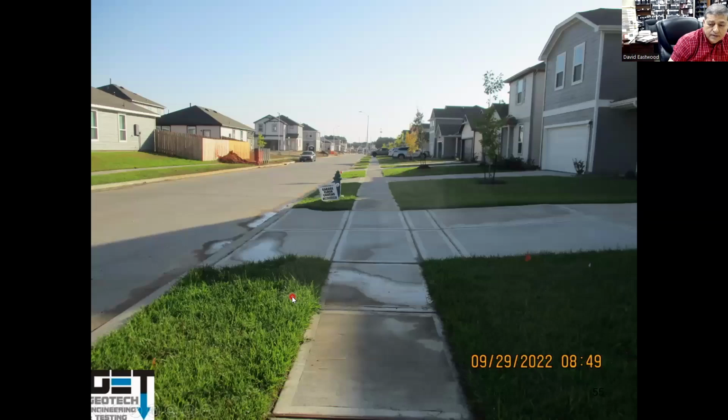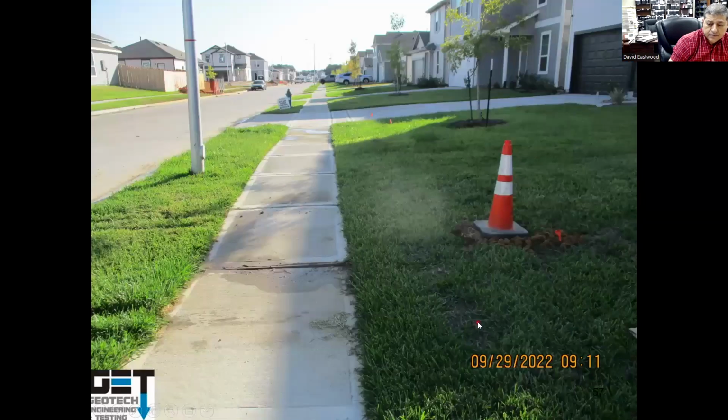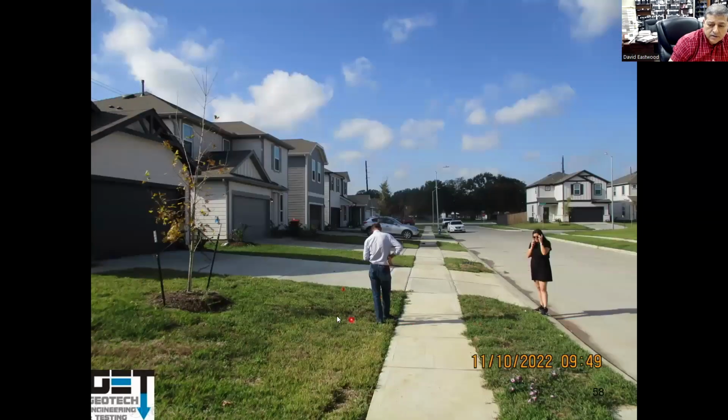Subdivision. Some of these subdivisions, they go in there and turn on the sprinkler system. Soils are sandy. When they get saturated, they start settling. So the sidewalks start settling. Brand new subdivision. Sidewalk settlements. Overwatering of the grass. See the grass is settling. Small area.